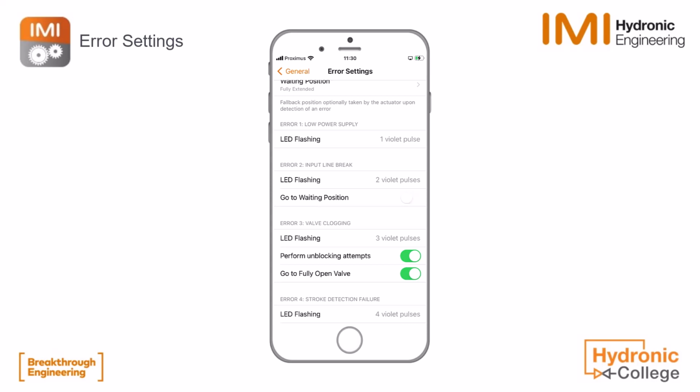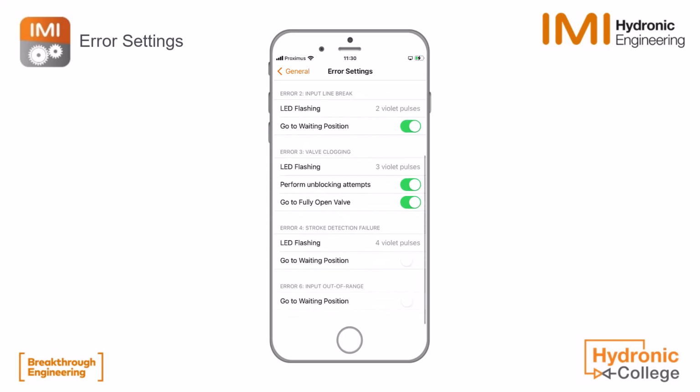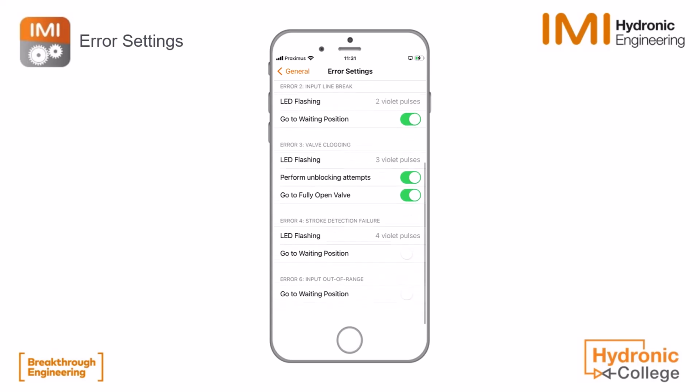Then error 2 is when input line break happens. We could set go to waiting position, so extended or retracted. Same for the valve clogging error I have spoken about. First of all, we can ask to perform some unblocking attempts, and then after several attempts it will go to a fully open valve in this case. As the valve is clogged, we can't shut it, of course.